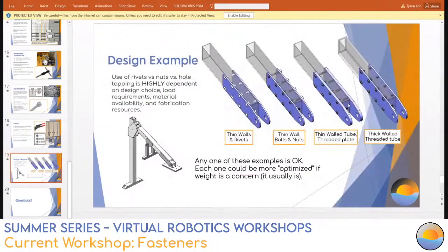It's something I wouldn't consider at our level. It's definitely doable to use bolts and rivets. Hey, top teams have done it. I know they do it. I don't think they're using aluminum rivets. So whatever stainless steel or steel rivet they're using, you need to have an appropriate driver for it. But at the end of the day, for a drive base, I go welded if you have the ability. But again, I haven't even talked about welding in terms of joining parts here. There's definitely a way we could have welded these parts together as well, and that would be the ultimate strength.